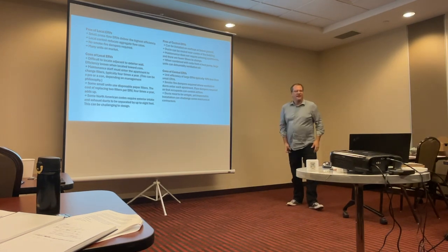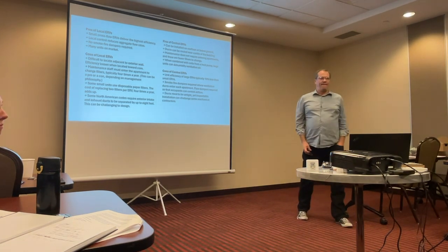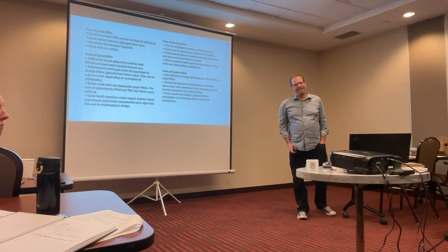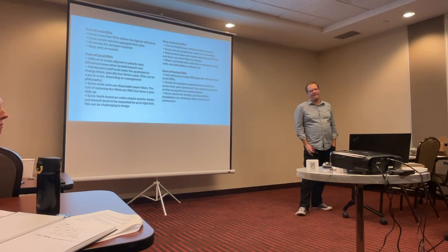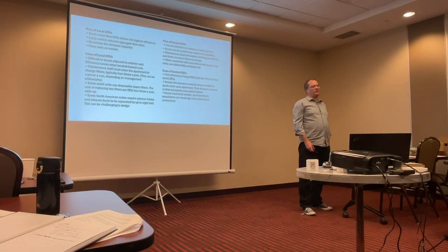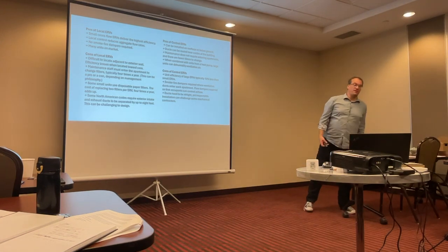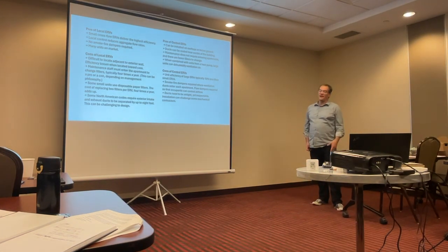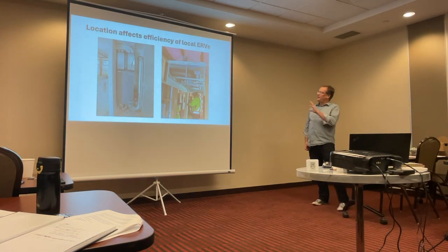Central allows you to add it to a standby circuit or an emergency circuit, so in the event of a power outage, you can keep the ventilation system going, unlike if you did it at a single unit. That's a strategy. That's worth noting. Also worth noting is the Passivhaus requirement. Passivhaus requires operable windows in every continuously used room. And research probably shows that people don't often use them. But in an emergency, you can. They're there, and that's part of why they're there. But yeah, it's important.